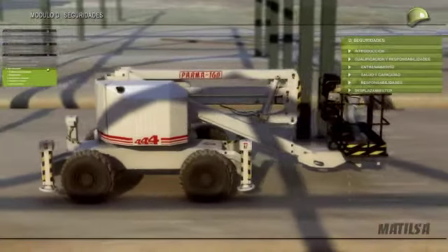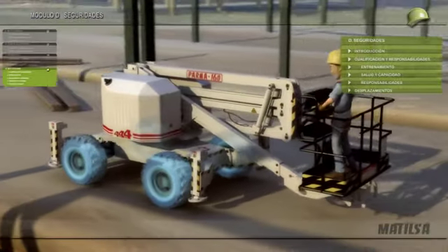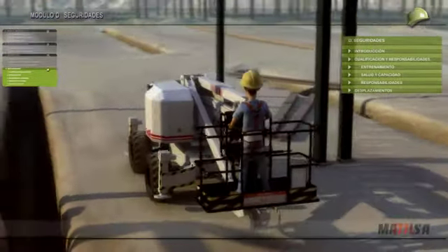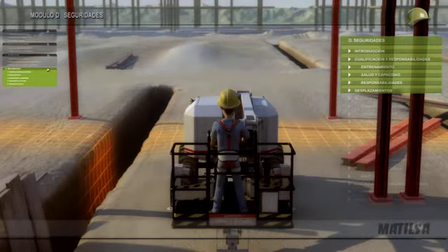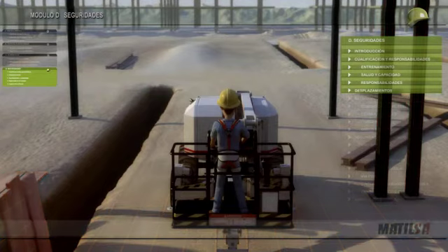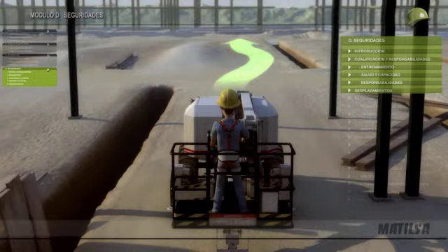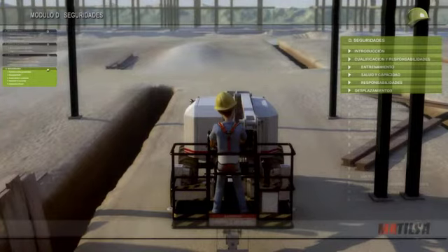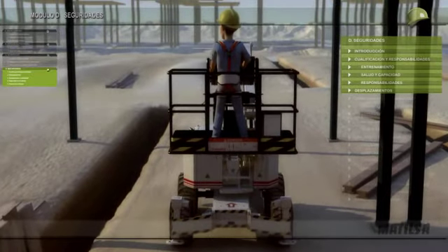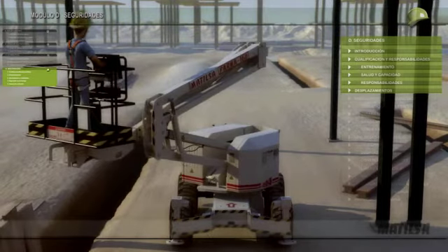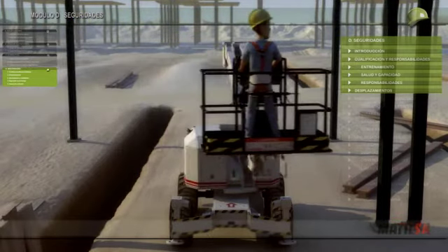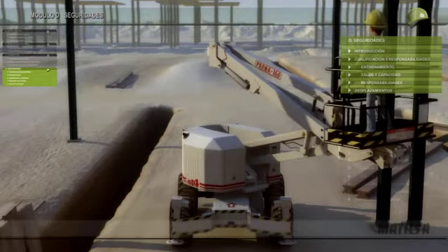Transport within the workplace. Make sure that your platform meets the requirements for moving itself over the ground. Before performing any movements, you will have to avoid ramps, ditches, slopes, or obstacles that may be a risk. Get to know the direction in which the platform is going and avoid transporting until you have inspected the non-visible places. Use the tower rotation in the case of an articulated or telescopic tower. If, however, you are using one of the scissors type, move yourself within the platform, making sure that all sides of the ground are safe in order to avoid accidents.